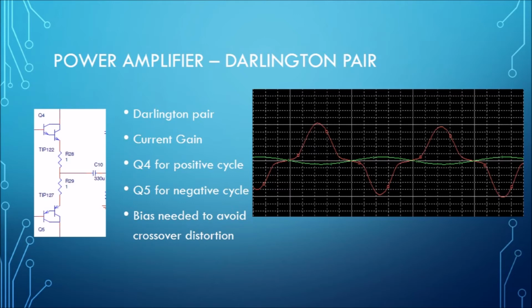The reason for this is that since these Darlingtons are made of BJTs, and BJTs need at least a bias of 0.7 volts between their base and emitter, the BJTs will not let through current until that happens. The way to fix this is to force a constant DC bias between the two bases of the Darlingtons.